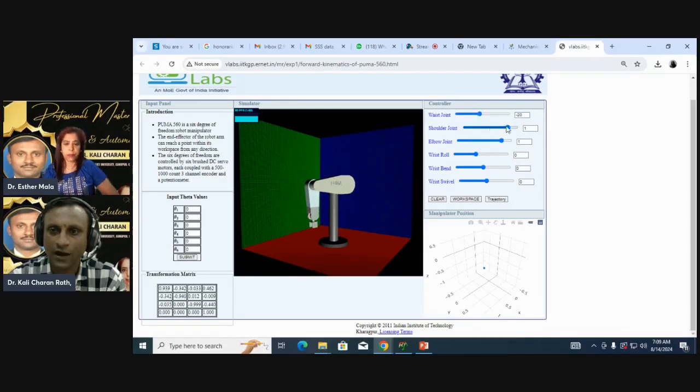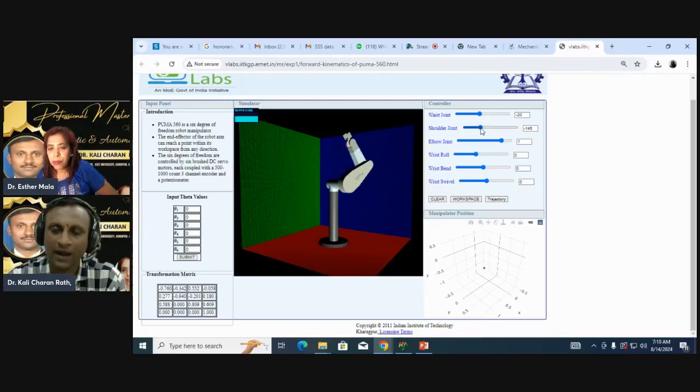Okay. Now when I change the shoulder joint, whose angle value is minus 225 degrees to 45, it will operate under this line. Now see, this is the shoulder line. This is now at minus 89 degrees, right? This one is minus 127 degrees. This is minus 145. Minus sense means, based upon the axis, the angle position will be as per the Cartesian coordinate system.